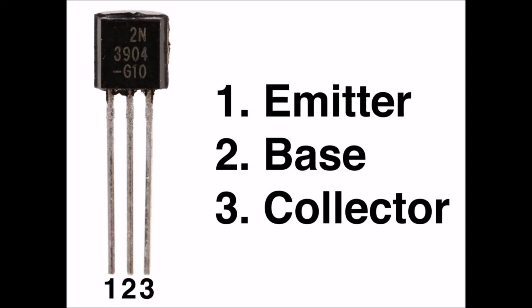The base-collector junction of a bipolar transistor is normally reverse biased. It will remain reverse biased as long as the EB stays smaller than the supply voltage between the emitter and the collector. In practical transistor circuits, engineers commonly set EB at a small fraction of the supply voltage. For example, if the battery between the emitter and the collector in figures 22.3a and b provides 12 volts, the small battery between the emitter and the base might consist of a single 1.5 volt cell.